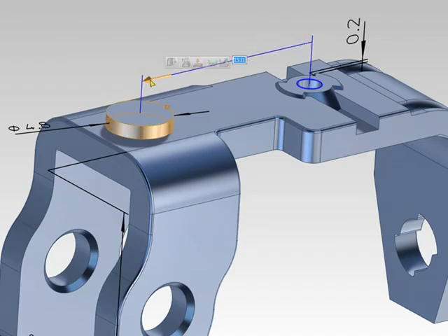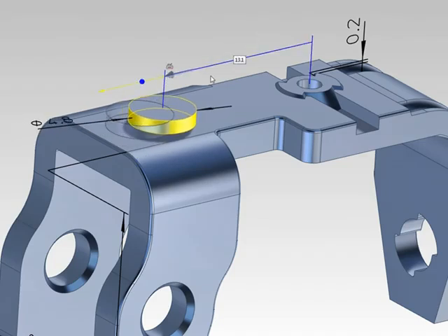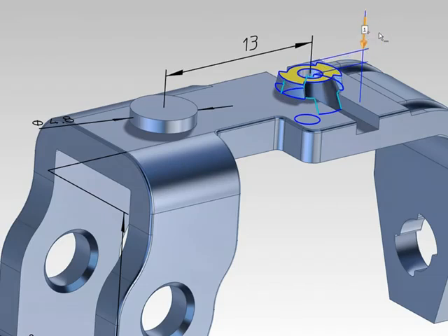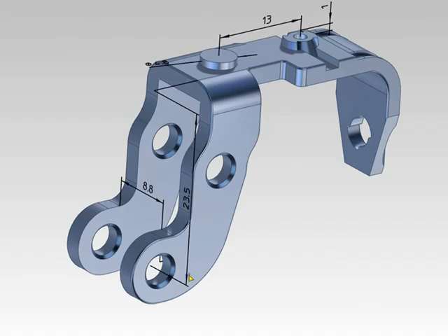I can also use 3D dimensions to drive the design change across groups of selected geometry, not just those faces that I've dimensioned. I can either drag with the 3D Copilot dynamically, or enter a precise value in the dimension field to define the change. Here I'll move both the hole and the outer faces in one move, while maintaining all the local relationships, like tangency.